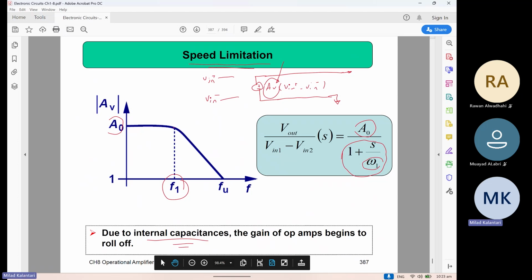Because you remember, in order to have these first order circuits, you need some resistor and capacitor, or some inductor and resistor, right? All of these cases can make poles. But where are these capacitors? They are inside the device. Let's say you are using a BJT device as the gain stage. Can you see where these poles are? Where are those caps?